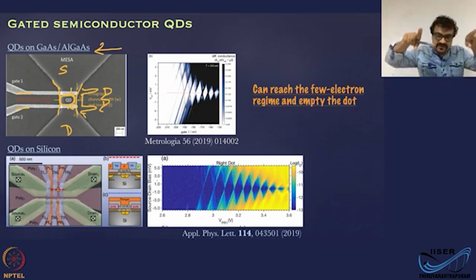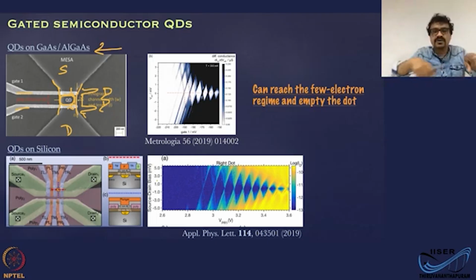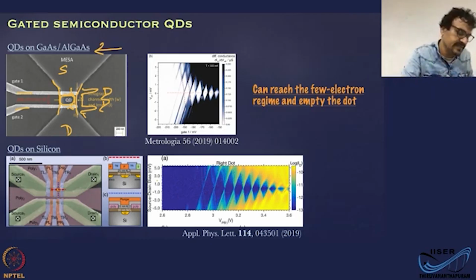Both effects will be there. So when you have the gate defining the quantum dot first, you'll have a large quantum dot. Then when you increase the gate voltage further, that means you'll make the tunnel barriers larger and also wider because of the electric field effect, or the fringing field, which is going to eventually have an effect of making the dot smaller and smaller. Okay. And that's what you're seeing here in this plot.